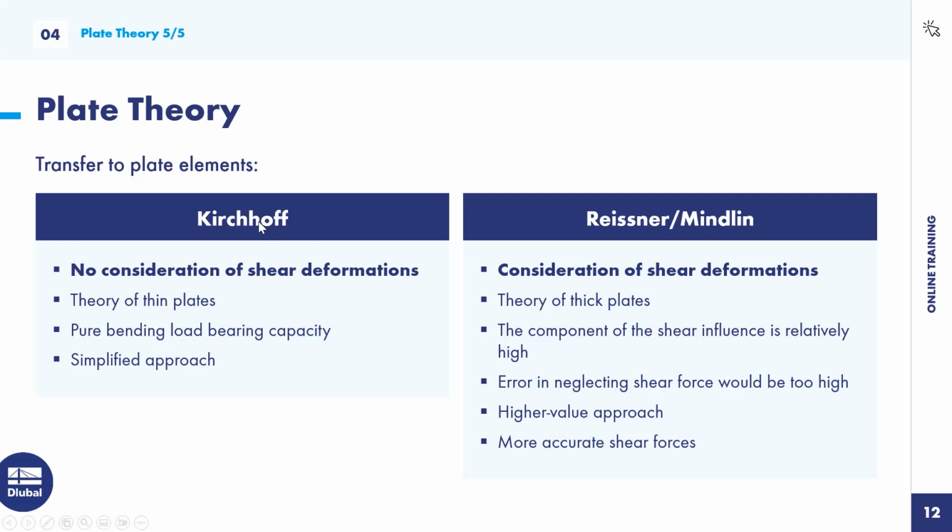But if you would try to solve it with a computer program, then the Kirchhoff would be way simpler. Let's stay with the Kirchhoff first. It's called the theory of thin plates since, as we learned before, the thicker the plate, the higher will be the influence of those shear deformations. That means this Kirchhoff theory is limited to thin plates.